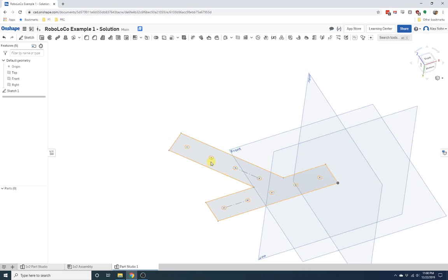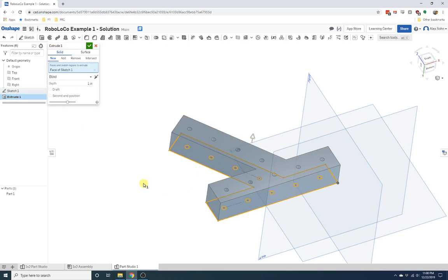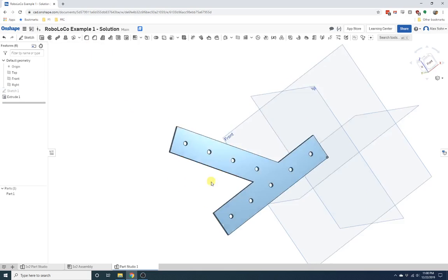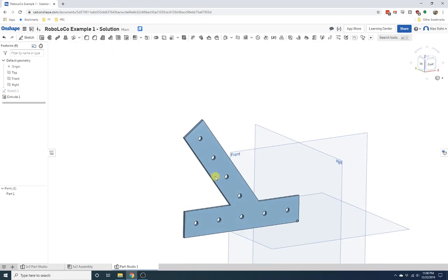So right now we're going to extrude this bracket. So we'll do extrude. It detects a sketch, and we're going to make it new. So I'm going to click here, and what is our bracket thickness? We're going to do 0.09. All right. So we're going to name it bracket. So the bracket is all on its own.